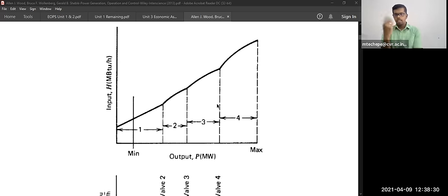In optimal power flow, the Newton-Raphson method and the Gauss-Seidel method, we are making a flat start. We are starting from 1 per unit. Full generation is being given to the particular sending end, and like that we are calculating. Like that we are making some considerations and some assumptions while solving the Newton-Raphson method.